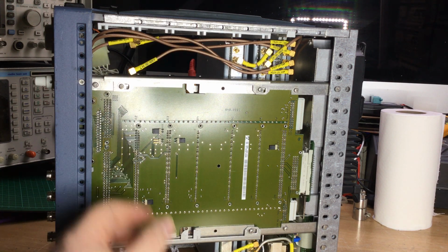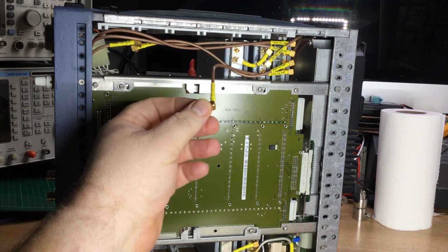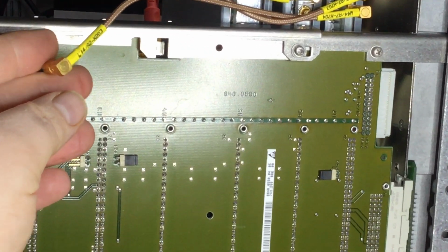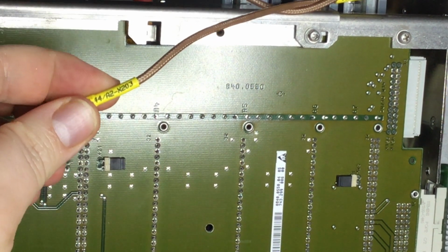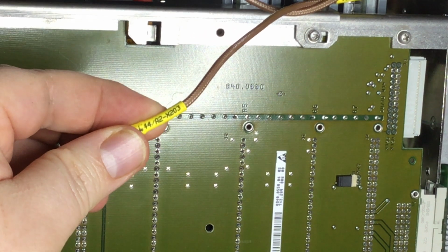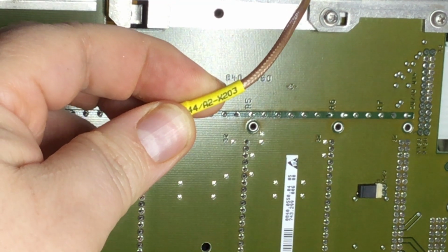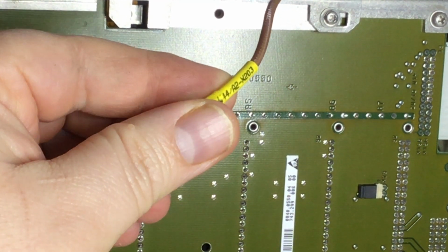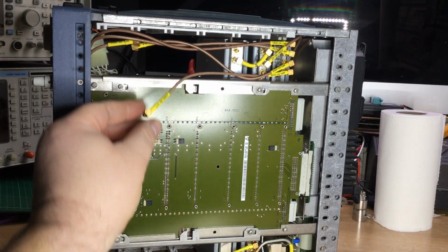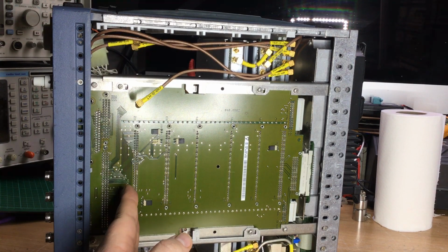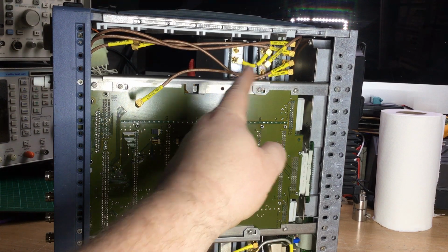Now earlier on we were talking about this, where we've got SMB plugs which push fit onto the connectors, and they are marked with an X number on them, and you can see there that's marked as an X number on that particular module there, X203 I think it is, looking at it through the camera. So that would plug into obviously X203 on the module, so long as you get one module in first and then connect the cables to that, because the other modules are so snugged up against one another.